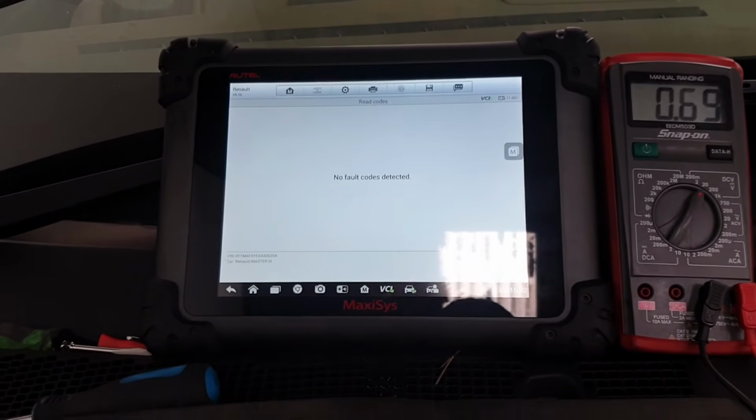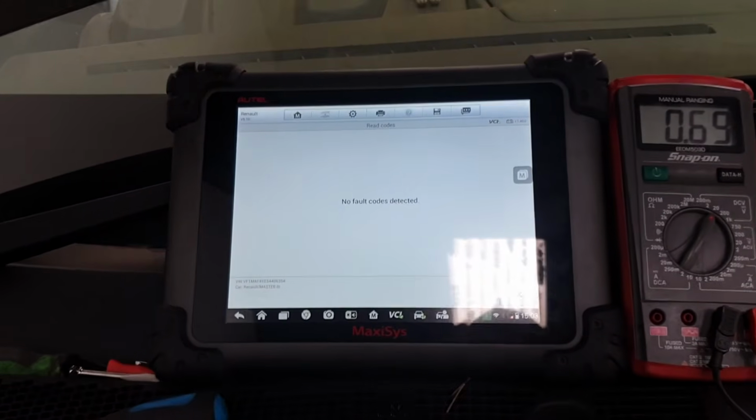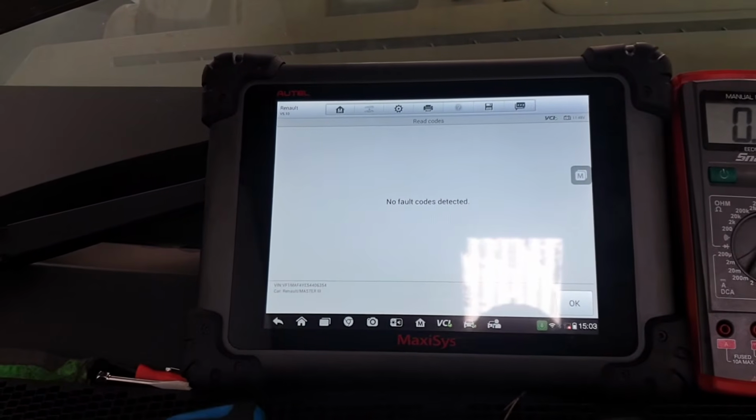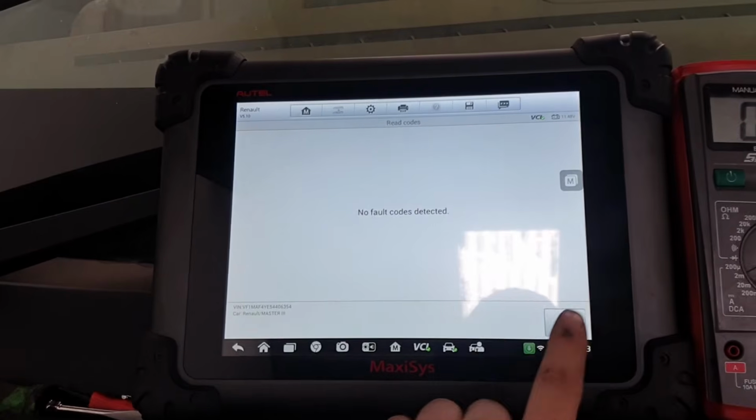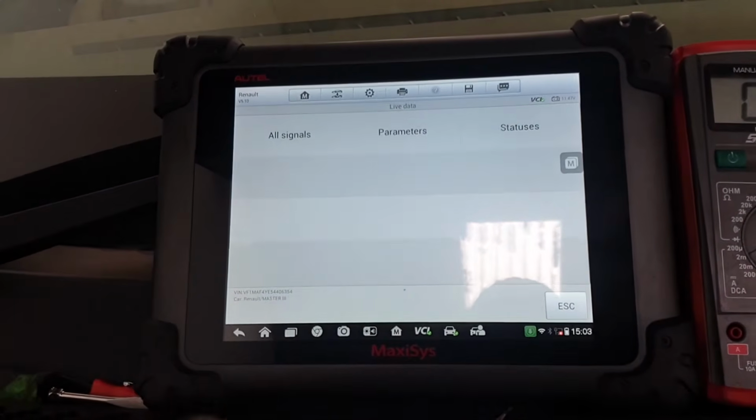So, as I suggested, the voltage ignition on was too high. The engine computer was seeing this and was setting a plausibility fault code. However, interestingly, the millibar parameter was reading 1000 millibar. Let's see what it reads now.